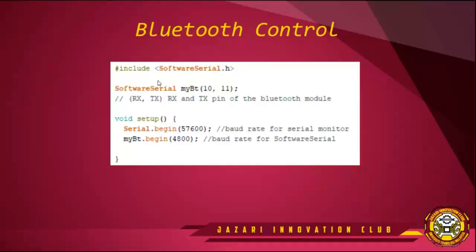So you just write the data type, which is the library name, and then a function name of your choice. Don't forget the semicolon and then the pins. Okay, so you're done. Declare the function of your Bluetooth module, and then you need to begin the function. So your name dot begin, and the baud rate for the software serial to use.